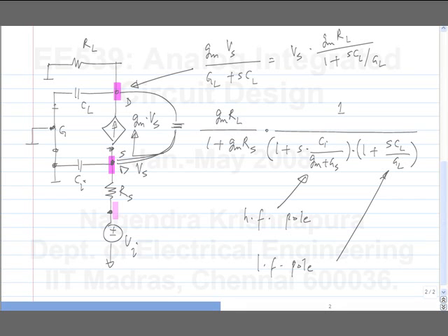Okay. Let's say you have amplifier 1, 2 and 3. Now you change something in amplifier 3, the gain of the first amplifier changes if you have a coupling across the second amplifier. Okay. Whereas a common gate amplifier will not have this coupling, so it provides a much greater isolation between what is before it and what is after it. Okay. So if you want good isolation between the input and output, a common gate amplifier is a better bet.